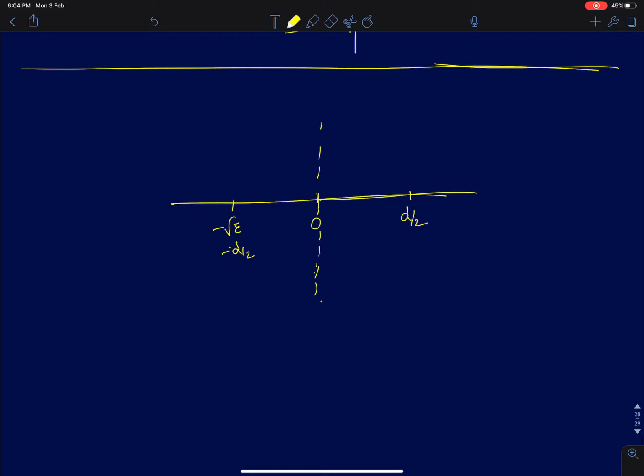Okay. Now how do you find the threshold? What should be my threshold for this receiver? That is determined by a simple relationship. Your goal is to minimize your probability of error. At the receiver, you should have minimum probability of error. That should be your goal. If you want minimum probability of error, then what should be your thresholding region? Let's take the simple case of binary symbols. I've transmitted 2 symbols. What should be my threshold such that the probability of error is minimized?